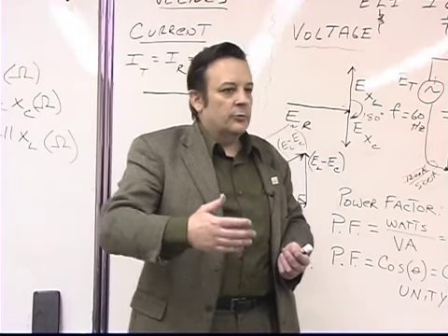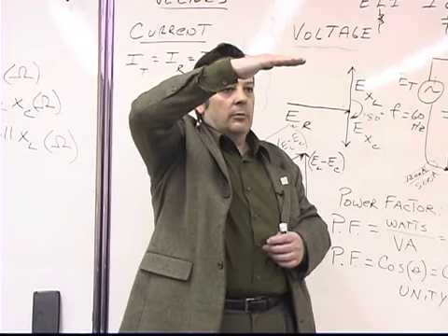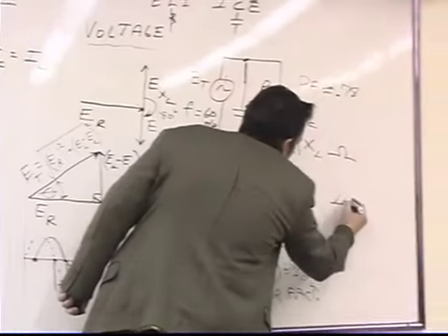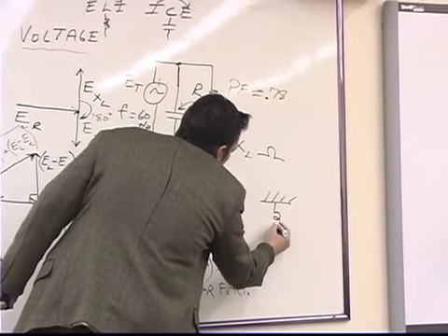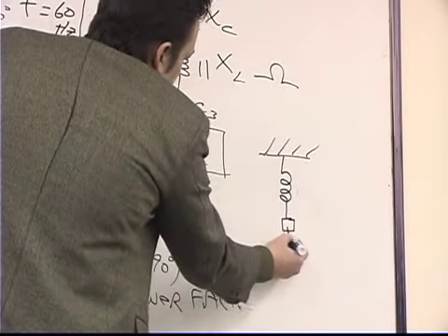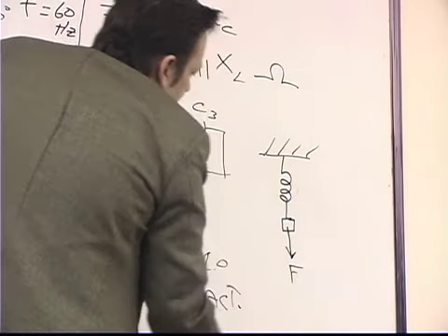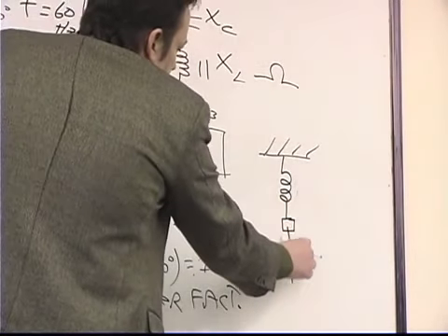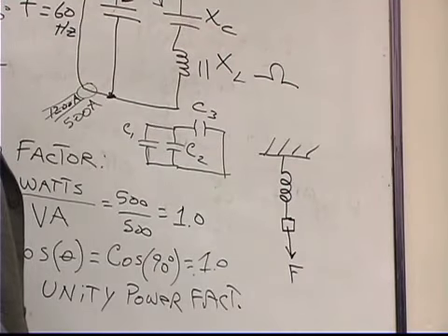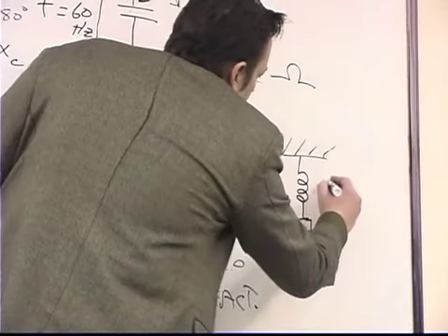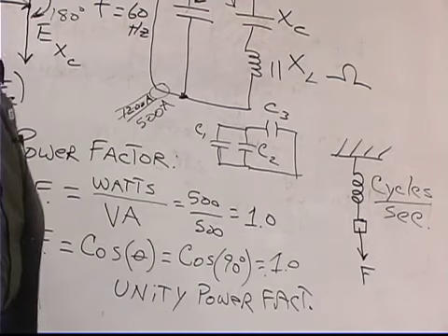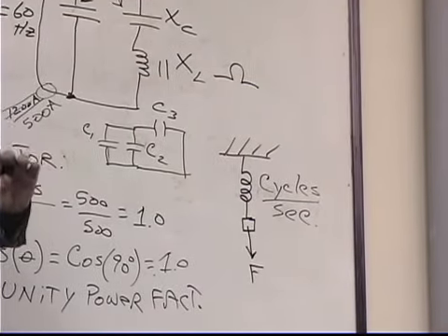And so in physics experiments, what we'll do is we'll take a rigid platform, we'll hang a spring from it, so it'll look like this. We'll have a rigid platform, we'll hang a spring from it, and then we'll put a weight on the spring. Okay? Putting a weight on the spring creates a gravitational force pulling down on the spring, and then what happens is the spring begins oscillating back and forth, back and forth. Even by inspection, you could get a fairly accurate count of the number of cycles per second that the spring was oscillating at. That would be what's known as the natural frequency of the spring.